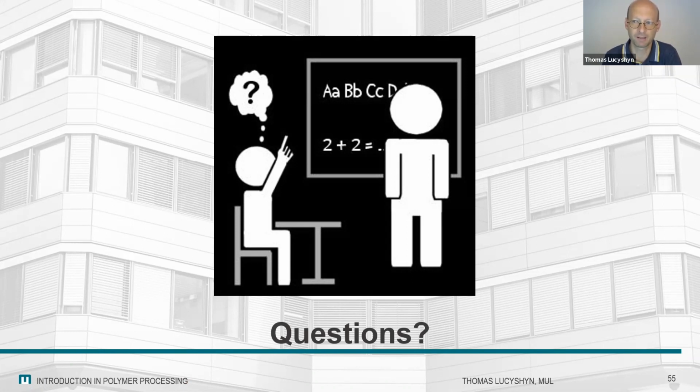It's basically a mixing. We have an extruder with typically twin screws, so 2 screws inside the extruder, which have a very good mixing effect. And there we are adding different additives to the polymer. And then in the end, the product of this process is basically pellets. And these pellets are then used in conventional processes to produce the real product.